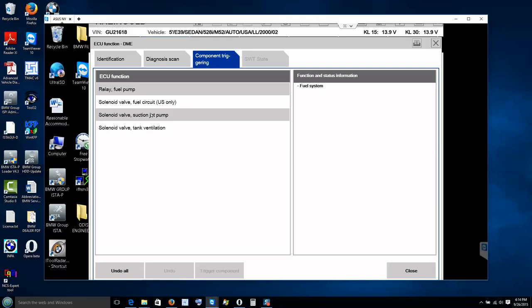Oh no, it's VIN specific, because BMW doesn't allow clusters to be switched between chassis because of the mileage data that is stored. They are different. But yes, you can manipulate it. You can take out the EPROM chip and put in another EPROM chip.